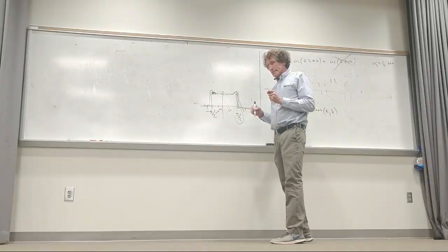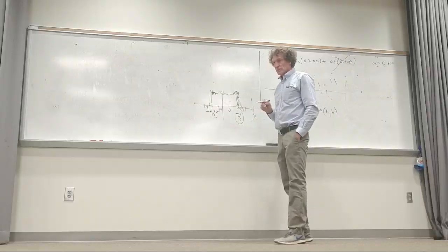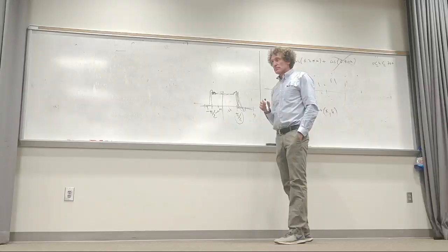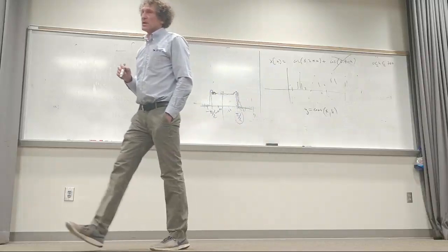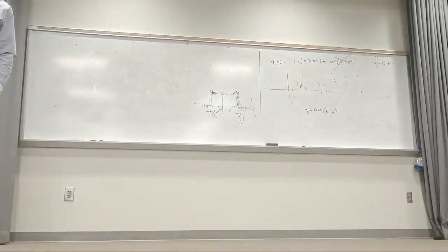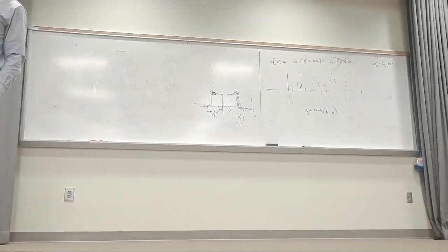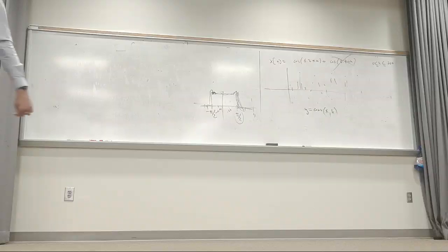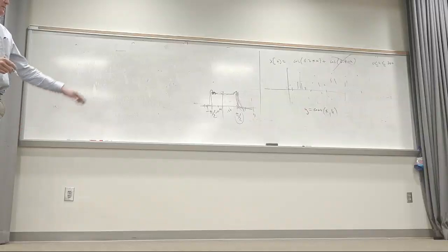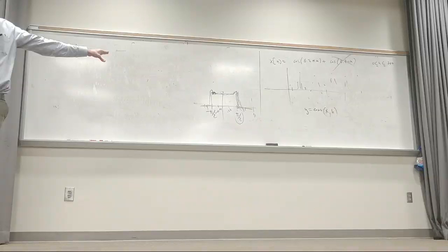Is that kind of like when we were doing the Fourier series and we had the overshoot because we had a finite number of cosines? You're talking about the Gibbs phenomenon. That's different. With Gibbs phenomenon, it doesn't matter how many terms you use; wherever there's a discontinuity in time, if you try to develop a Fourier series to represent a periodic function, you're always going to get that overshoot, undershoot and ringing. The more terms you use, the shorter the interval of the ringing is. But you still get that overshoot, you cannot help it. This is different. This has to do with the finite number of terms.